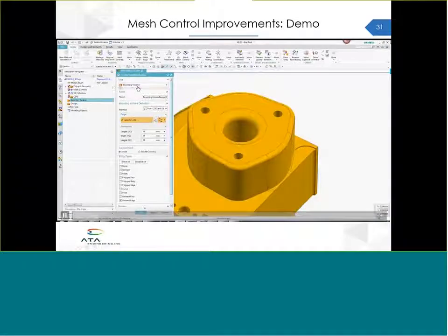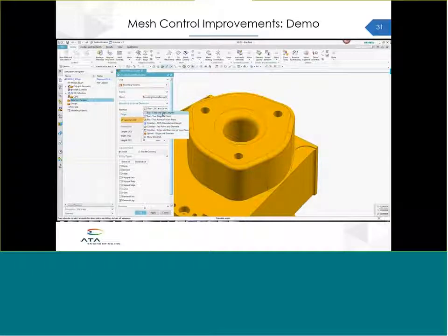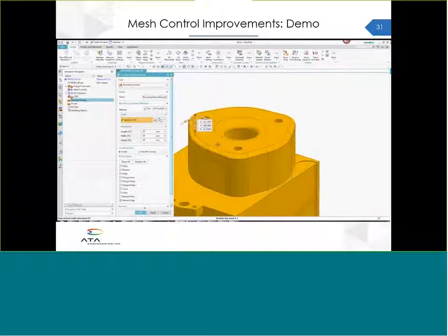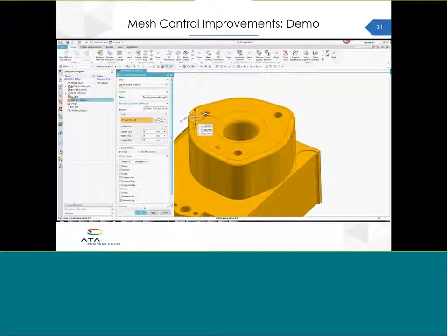I'll go ahead and hide the 3D mesh to make it easier to see. And then you have a bunch of different methods for your bounding volume definition. I'm just going to use the default coordinate system and edge lengths option. So now I can click anywhere on this polygon body. And so you have a few different options of how you want to specify your volume box.